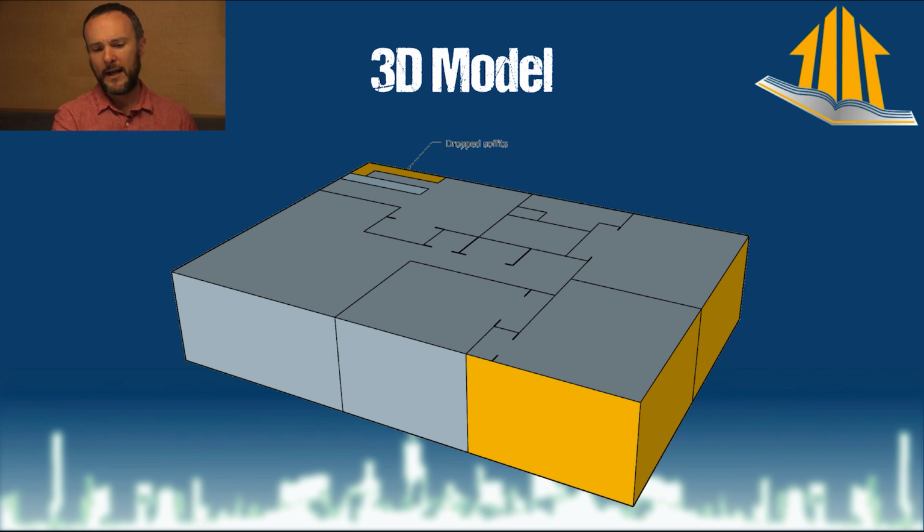That being said, what I could do here is two different kinds of load calculations. I could do what's called a block load, which is taking this rectangular floor plan and then just multiplying it by the ceiling height of the entire thing and doing one block. That would be one big cube. That's called a block load, and that gives you the heating and cooling necessary for this entire place.